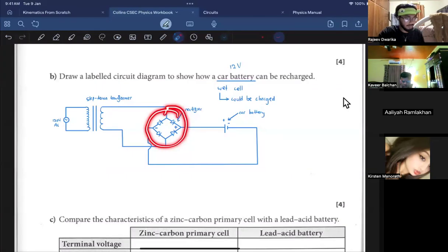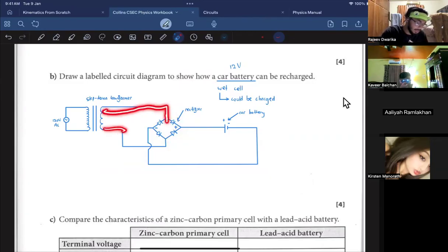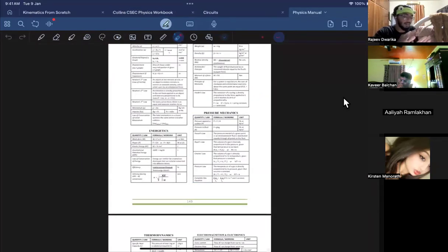It has 4 diodes. Unfortunately, you need to remember this. You need to remember the orientation of the diodes. So you have two diodes pointing in the opposite direction, like these diodes over here pointing in the same direction, and these diodes here pointing in the same direction, right? In the middle of them, you're connecting it to the alternating supply. The other two connections are the direct current.